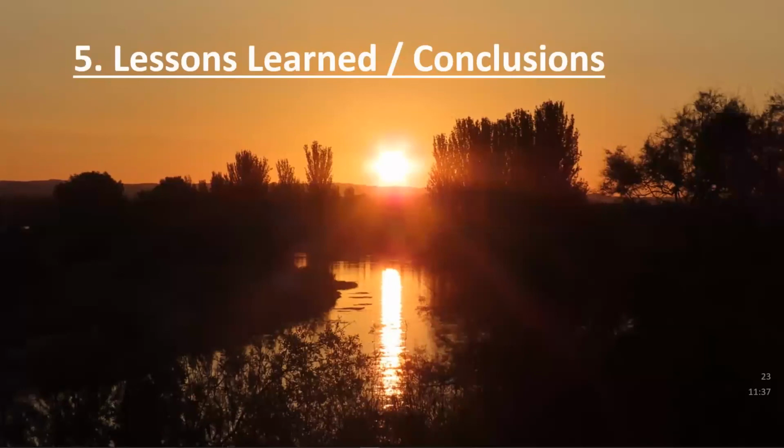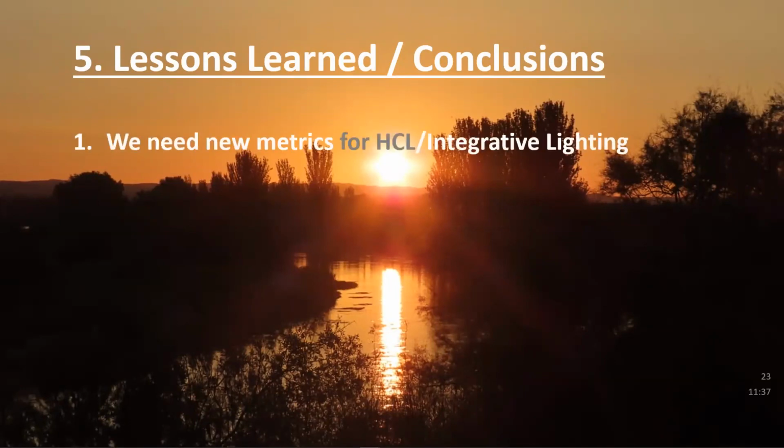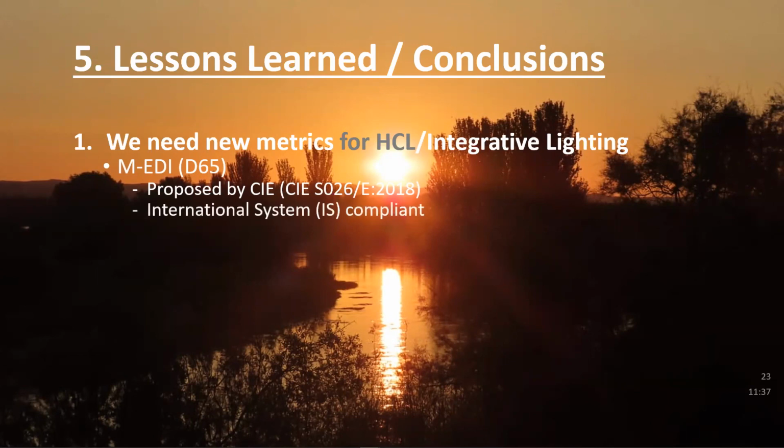So, which are the lessons learned in this presentation? That we need new metrics for human-centric lighting, integrative lighting. The main one is the melanopic equivalent daylight illuminance, D65, that has been proposed in the document CIE S026 2018. And it is International System of Units compliant. No other one is.